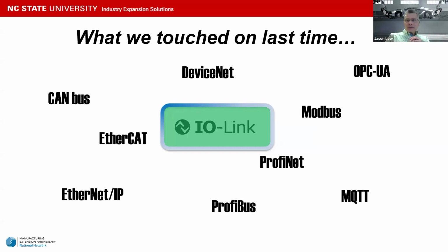And what I like to say the most about this other information is to think about it being the health of the sensor. So is a lens on a photo eye getting dirty? Is the sensor element or whatever is doing the sensing getting weak?